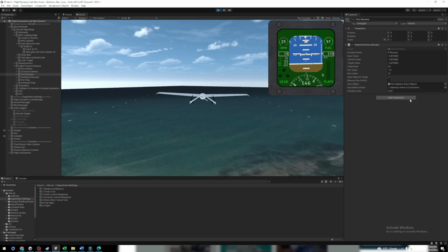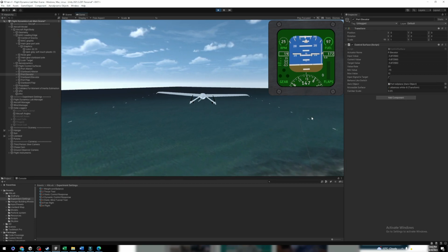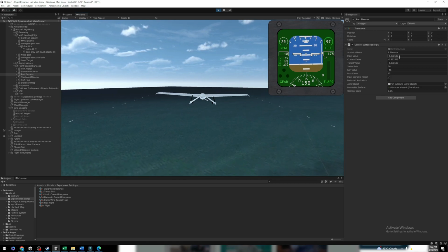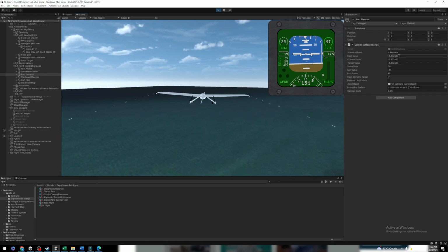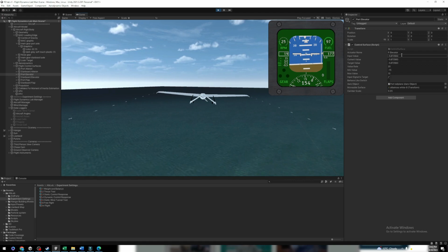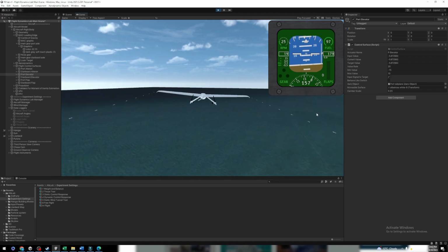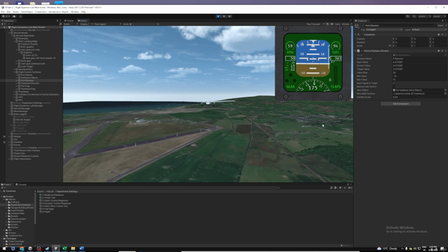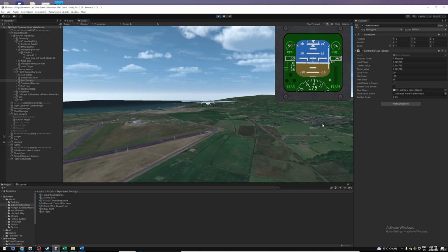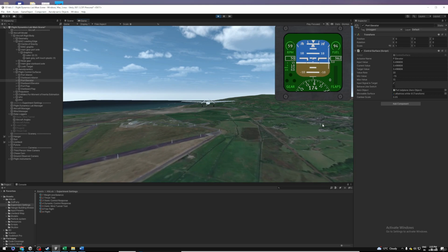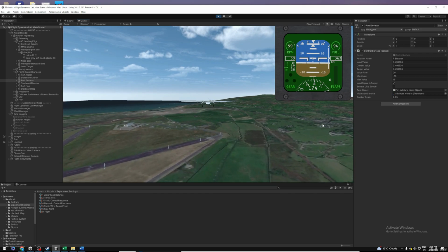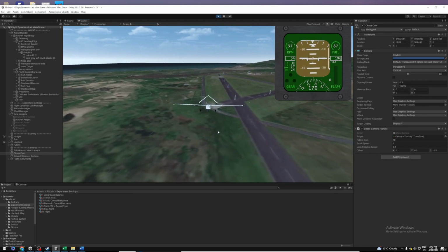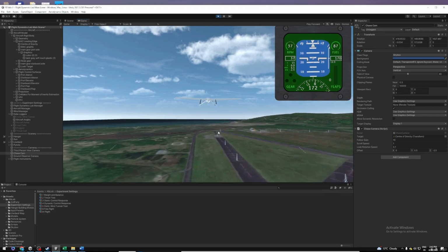During this test, the goal was to trim the aircraft at around 20 meters per second, as shown. The Albatross flew at 25 rpm with an elevator trim angle of negative 5.87. Also, the maximum speed the aircraft attained while maintaining trim was approximately 50 meters per second, as demonstrated in the video. Next, the phugoid motion of the aircraft was examined.